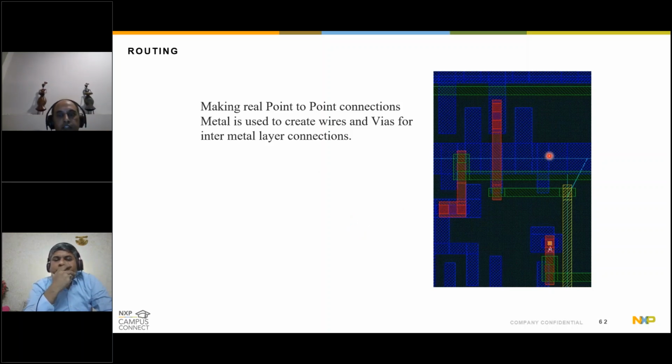So you can imagine this view geometry is, let's say, probably the VDD or the ground rail connecting the different standard cells' VDD rails together, and then you are connecting the pins of one standard cell to other standard cells, and these different color geometries, let's say blue to red. This is where the layer hopping is happening, and wherever there is layer hopping, the vias will come into the picture, which make the physical contact between the upper and the lower metal layers.